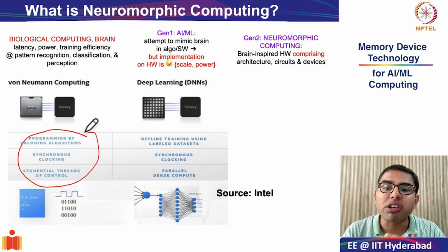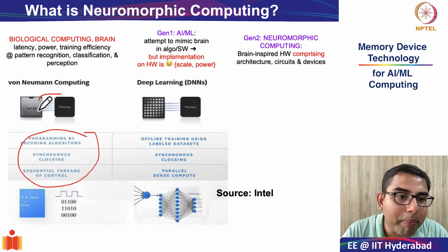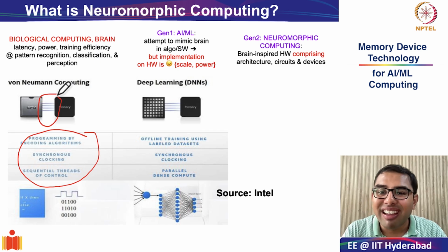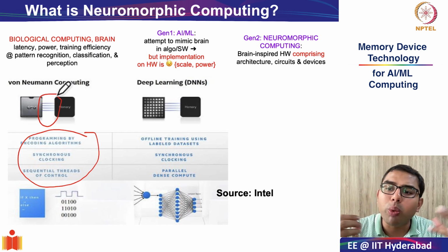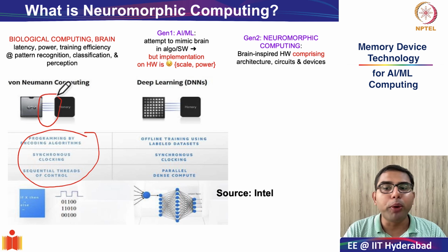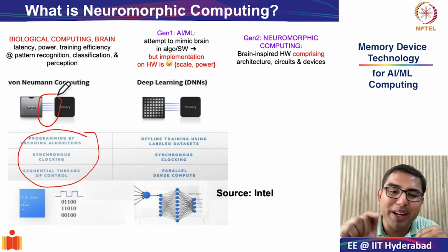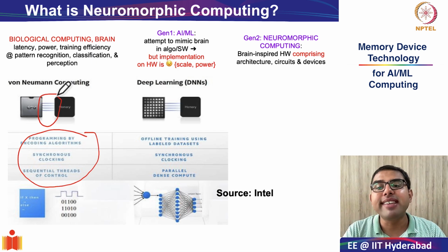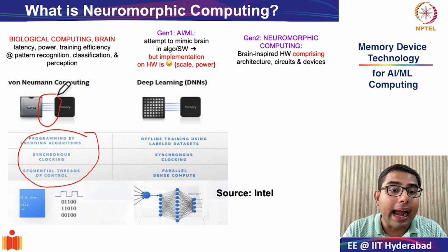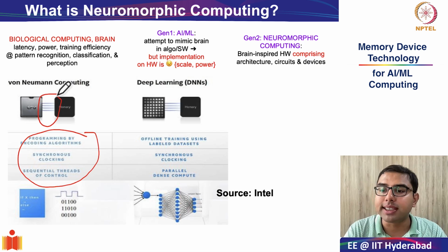So all these instructions and data must shuttle back and forth over this shared bus, which connects the logic element and the memory element. This is quite efficient for general purpose computing, but it suffers from the von Neumann bottleneck, especially in data-driven computing. With its limited bandwidth and sequential execution, and so much power being wasted in shuttling data back and forth rather than the actual compute process.